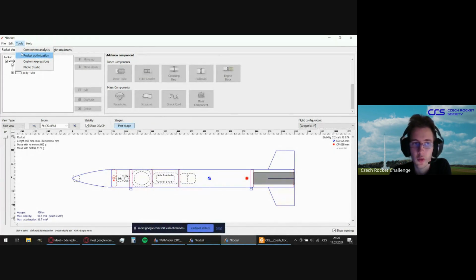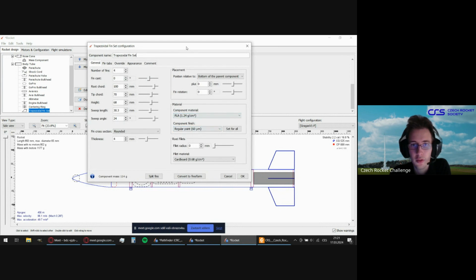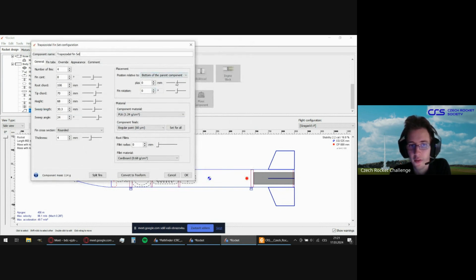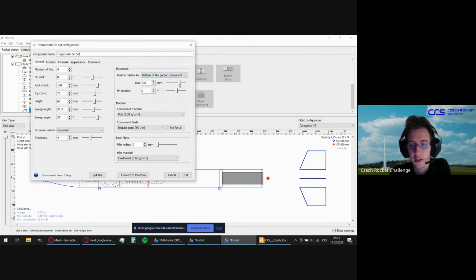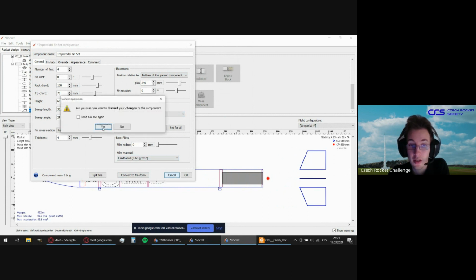You need to carefully restrain the optimization because, for example, if you are trying to optimize the shape of the fins, if you don't constrain it correctly, basically the first thing it finds out is that this is the best stability that you can have. And the software is not wrong, but you will never manufacture this, of course, so just be careful with that.